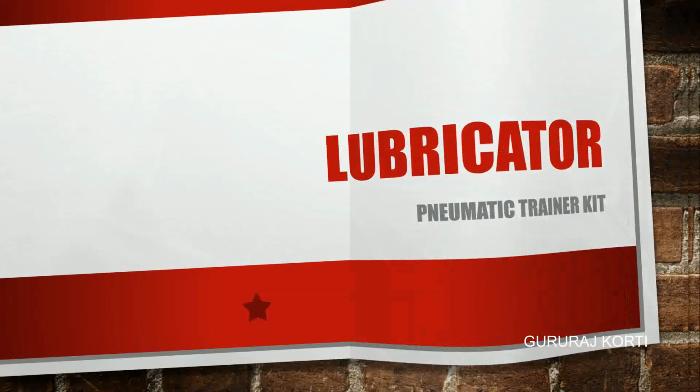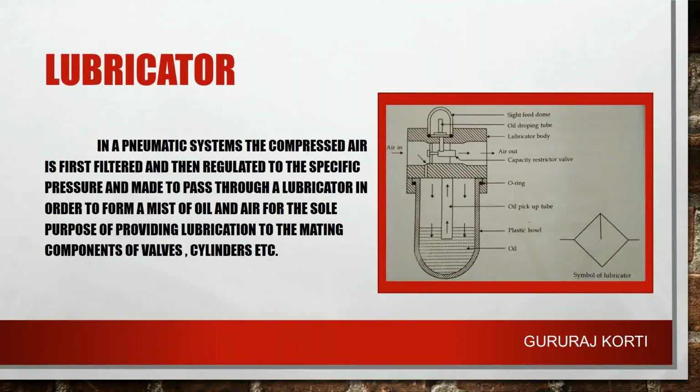Lubricator. In pneumatic systems, the compressed air is first filtered and then regulated to the specific pressure and made to pass through a lubricator in order to form a mist of oil and air for the sole purpose of providing lubrication to the mating components of valves, cylinders, etc.